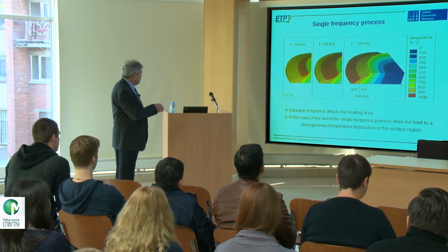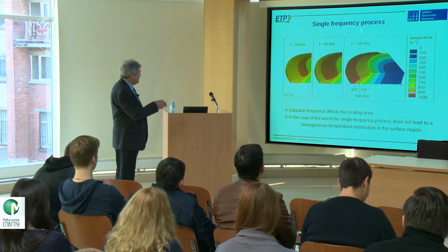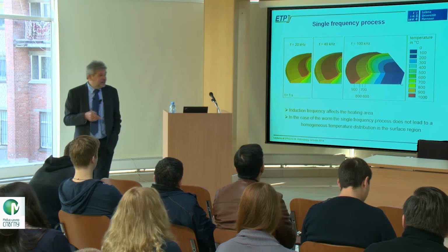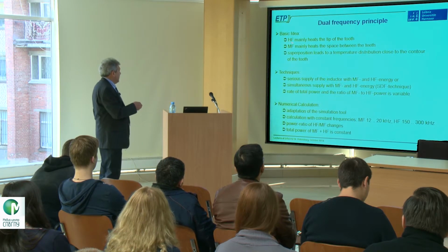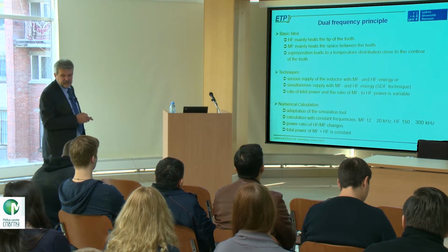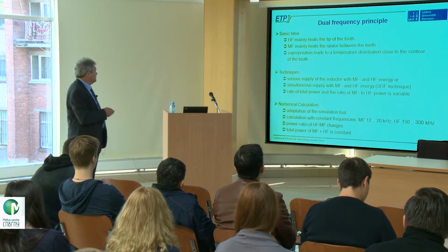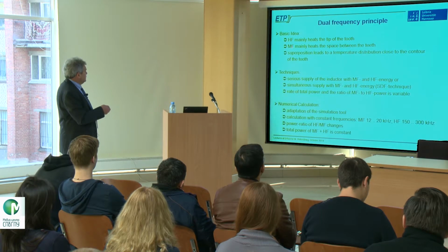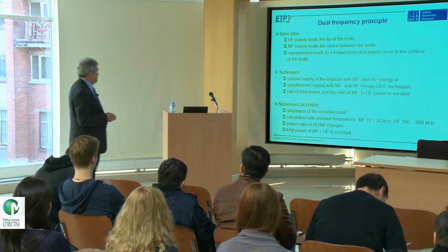If you use low frequency, you heat the bottom area, the foot area. So the idea is if you can combine this, with both frequencies, then you have a homogeneous heating. And this is the idea. You need high frequency. HF stands for high frequency. In English, typically radio frequency, RF, but here in induction, HF is used also in English language. High frequency mainly hits the tip of the tooth. Medium frequency, the space between the teeth, so the bottom parts. And the superposition should lead to a more or less homogeneous contour hardening.